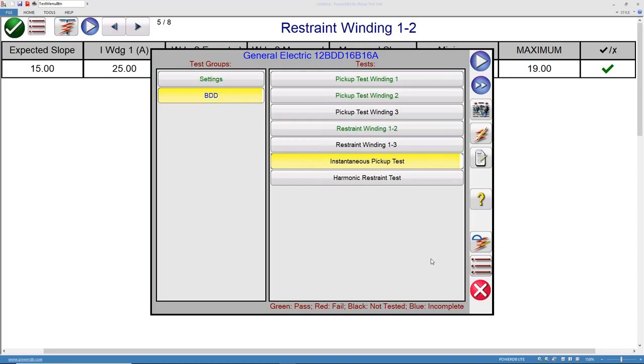Thanks, guys. Well, the answer is of course you need to test when you have a relay and you have 3 windings, like the relay that David was showing there. If the 3 elements are being used, because you have, like you say, a 3 winding transformer, then you need to test all the elements that are enabled in the relay at the moment of the testing.